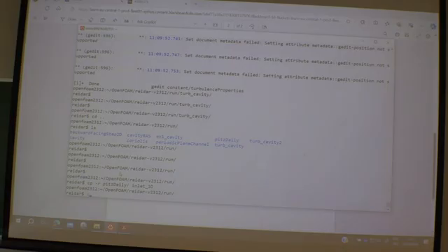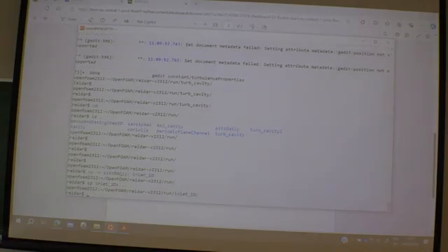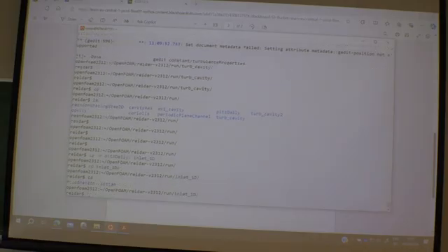Let's go into the inlet_1D case here, and then I copy from our turbulent cavity the system blockMeshDict. There we have the mesh, and I want that one now overwriting my blockMeshDict in my new system, something like that.